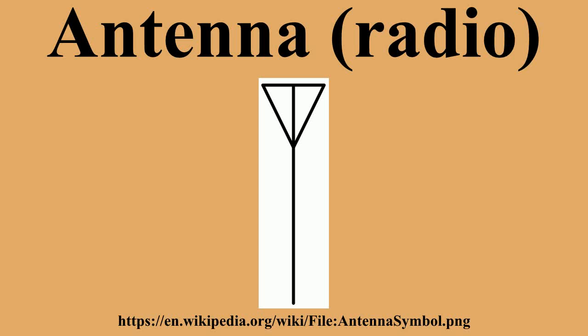For instance, a phased array consists of two or more simple antennas which are connected together through an electrical network. This often involves a number of parallel dipole antennas with a certain spacing, depending on the relative phase introduced by the network. The same combination of dipole antennas can operate as a broadside array or as an end-fire array. Antenna arrays may employ any basic antenna type, such as dipole, loop or slot antennas. These elements are often identical.